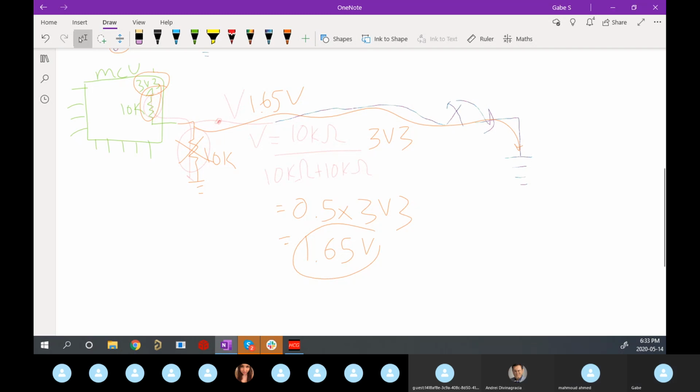That's a good question. I don't know. I haven't had, because what you're doing there is letting it float into some state, right? So it's either going to pick a 1 or a 0. And I've never had a situation where I don't care where it floats to. Usually I want it to be in some defined state. If you can think of something where you'd want it to just be random, maybe like making a random number generator with an input pin.